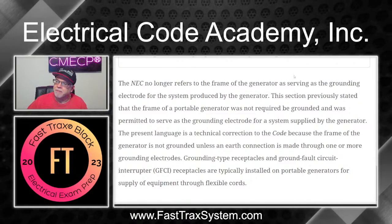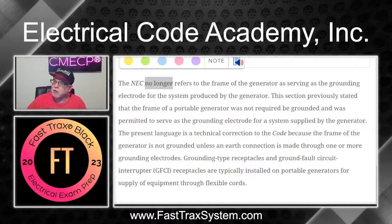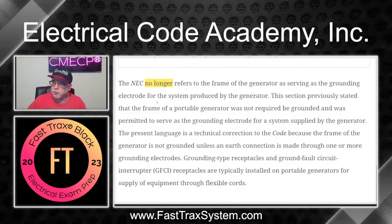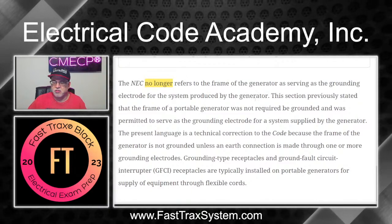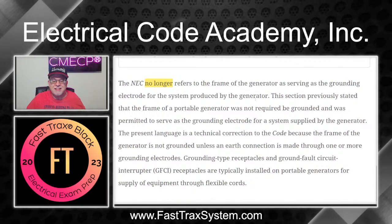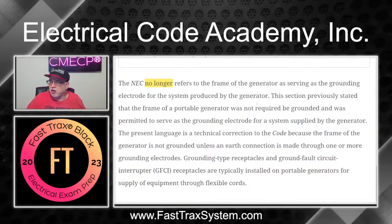So let me read it here. It says the NEC no longer refers to the frame of a generator as serving as the grounding electrode for the system produced by the generator. It can't be, because the whole premise here was it doesn't have electrodes. It's not connected to Earth.